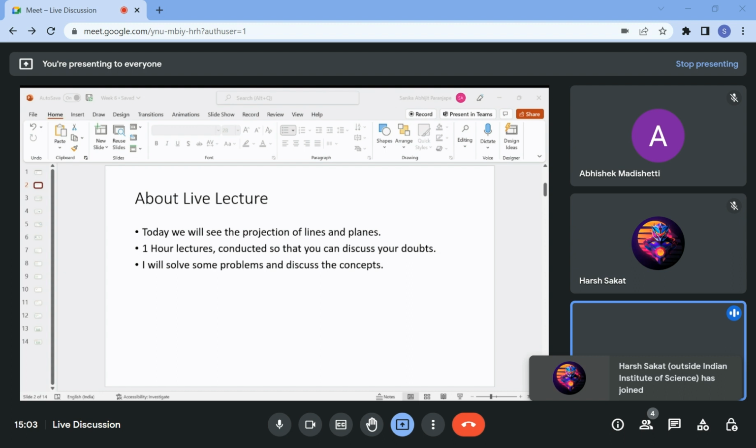So this pencil can rotate anyhow, so this is now going to trace a horizontal cone and it will trace a circle in the vertical plane. And since it is moving like this and I'm not changing the angle with respect to VP, I'm not changing this angle that I can see in the top view with respect to VP.